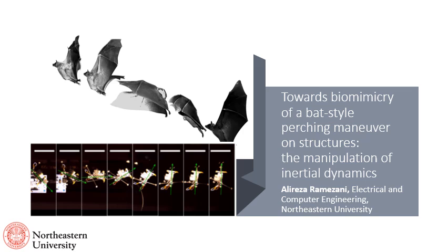The key hypothesis this work tries to inspect is the feasibility of performing flip turns, a well-known attribute of a bat-like landing maneuver, through the manipulation of inertial dynamics while excluding aerodynamic forces. Bats possess no energy-hungry motors widely used in flying robots for thrust vectoring, yet they are more capable than any of these systems when agility and, of course, energetic efficiency of flight are concerned.